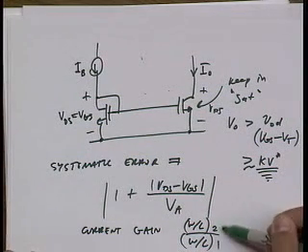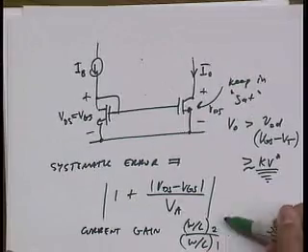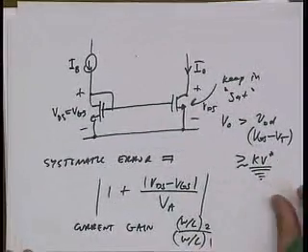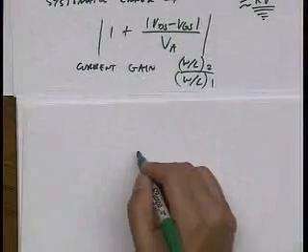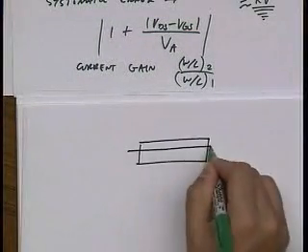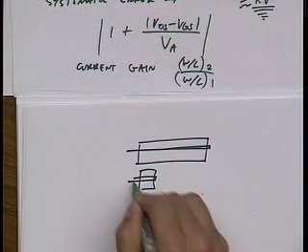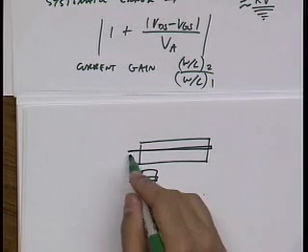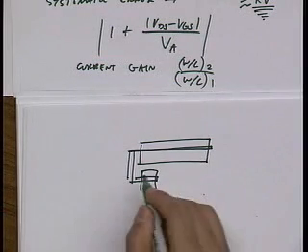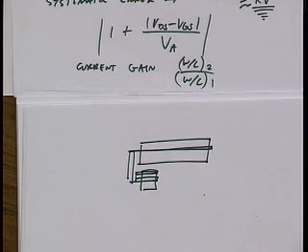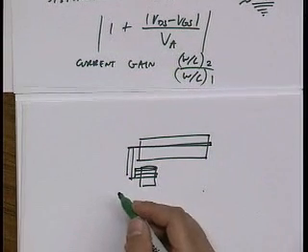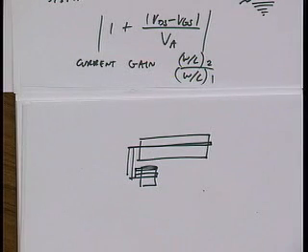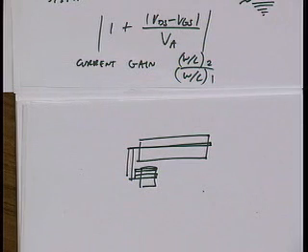But the important point is that if I'm going to scale W over L's, I definitely want to do it with copied devices. So the dumb way to do it would be this. Right? This is my minimum size transistor. This is my wide transistor. I connect my gates together. And this one is a diode connected device, right? This would be really stupid. Why is that? Yeah, the devices don't really match.